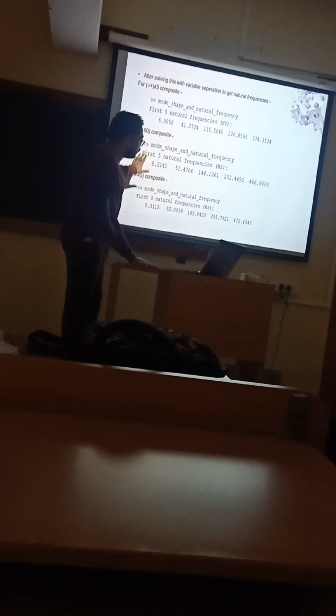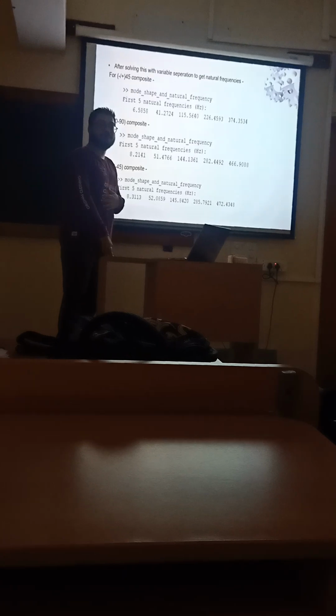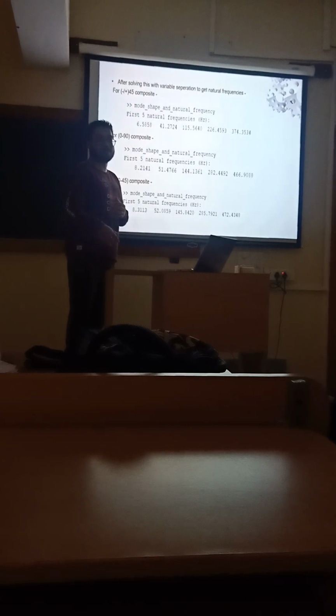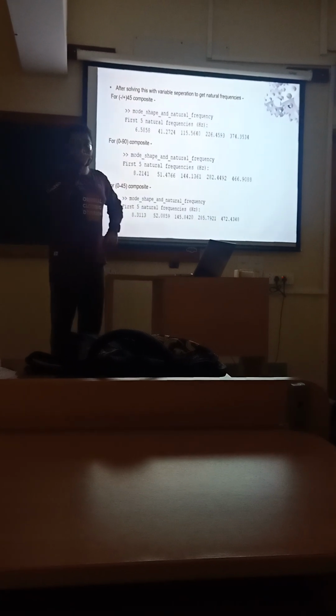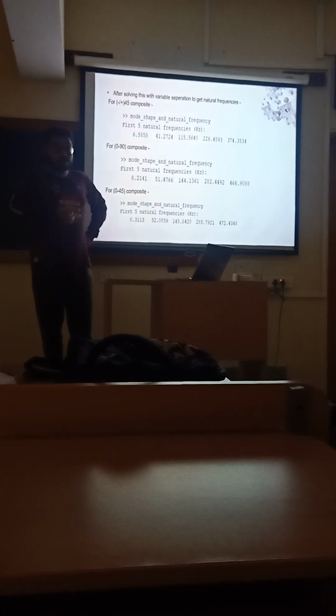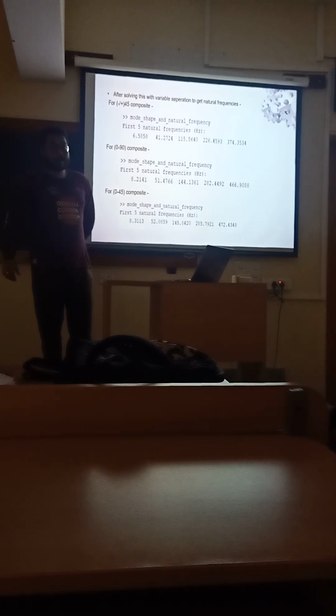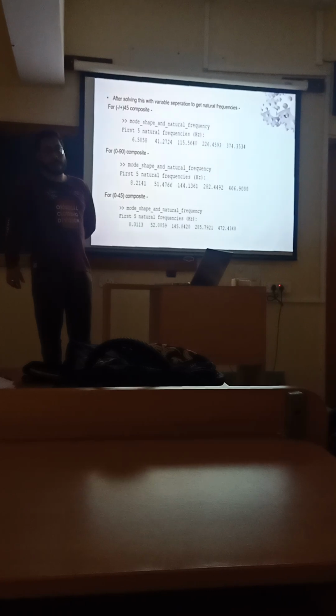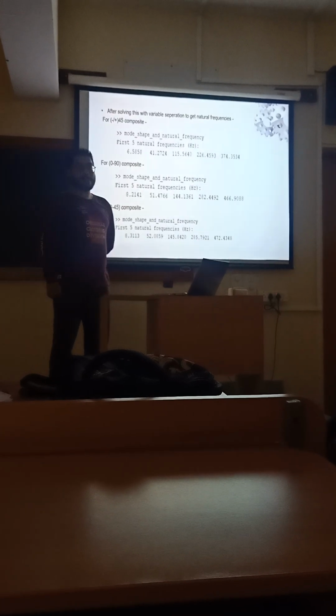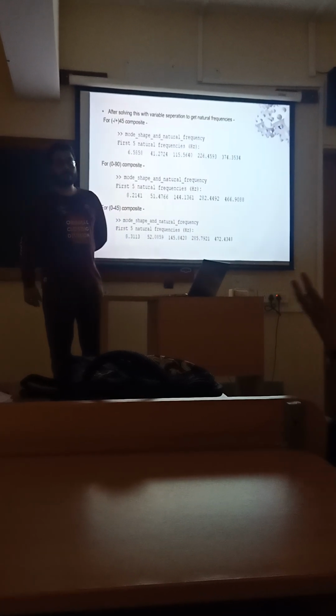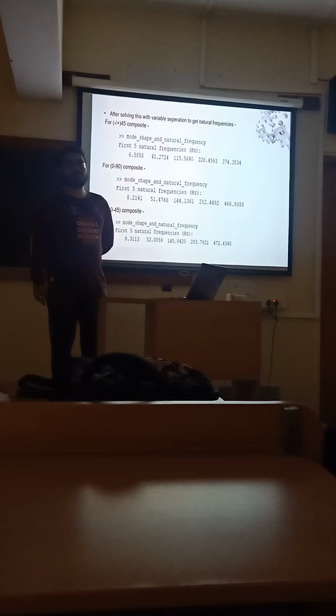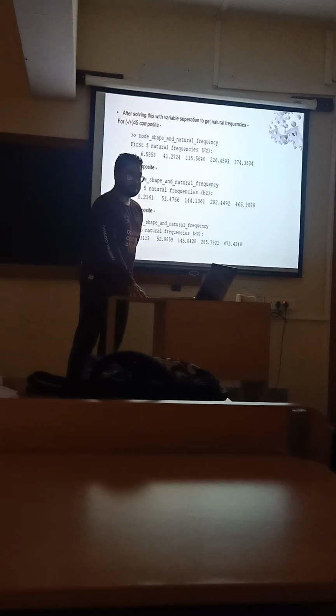mode shapes. Generally, is it always that higher mode shapes are more complex? The higher modes' geometry depends on the width and thickness. Okay. If the width is more and more, it will become like a plate, and then bending and torsion modes will start coming. Because of that, the shape will start forming.